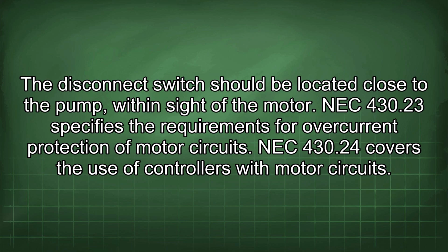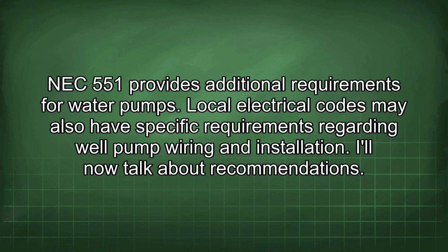NEC 430.23 specifies the requirements for overcurrent protection of motor circuits. NEC 430.24 covers the use of controllers with motor circuits. NEC 551 provides additional requirements for water pumps. Local electrical codes may also have specific requirements regarding well pump wiring and installation.